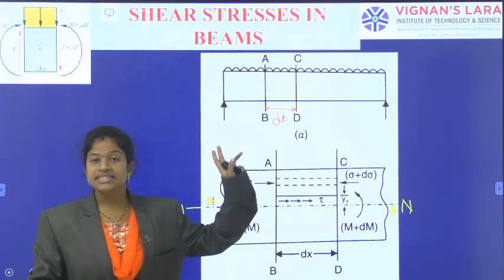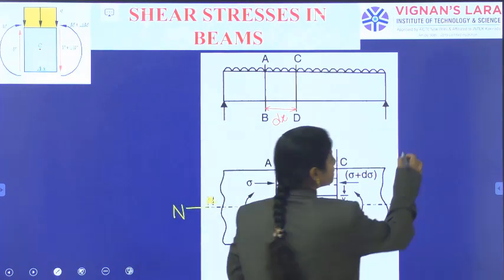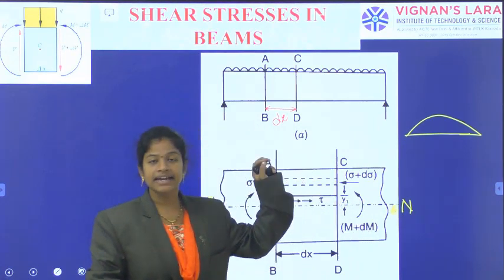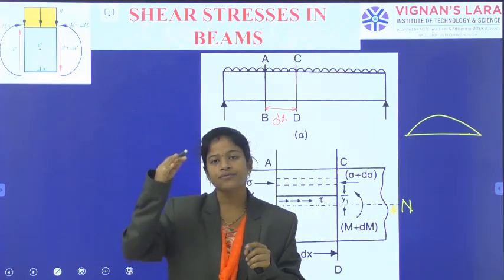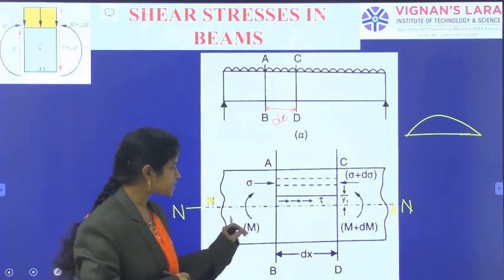As in a simply supported beam with UDL over entire length, what is the bending moment diagram? It is like this, right? Completely sagging type moment. Either it is 0 or some value, but it is purely sagging type. That's why it is having pure sagging type indication.